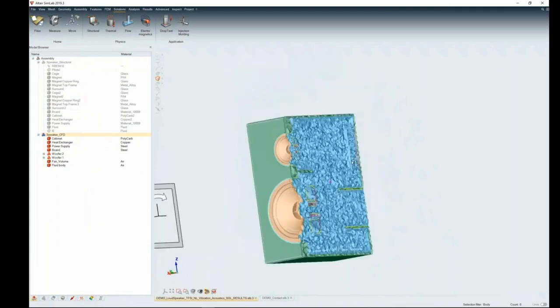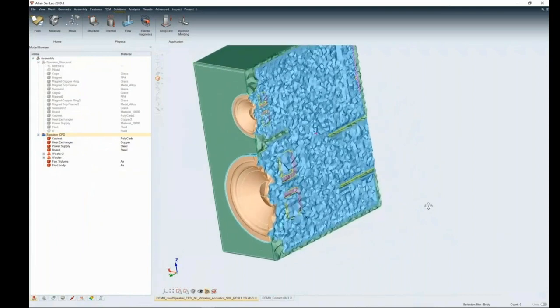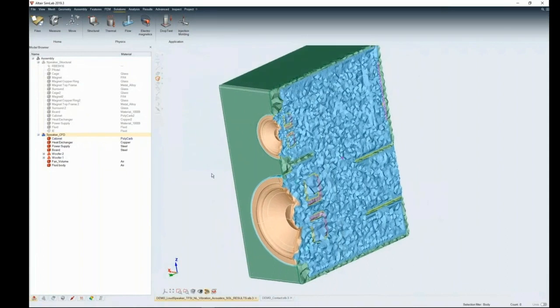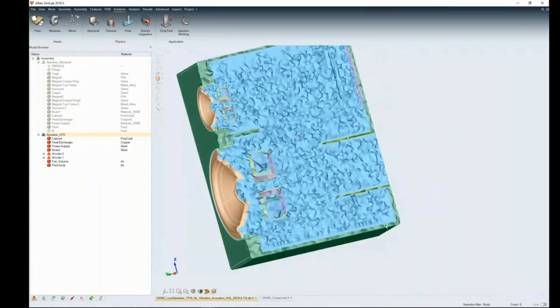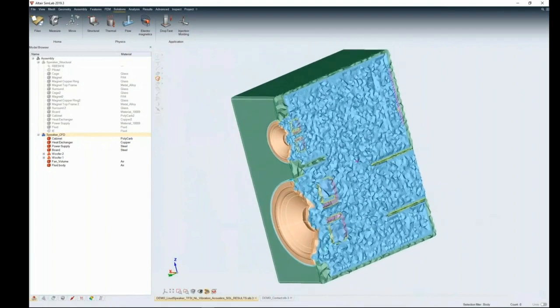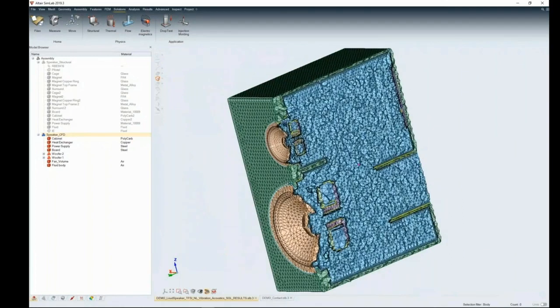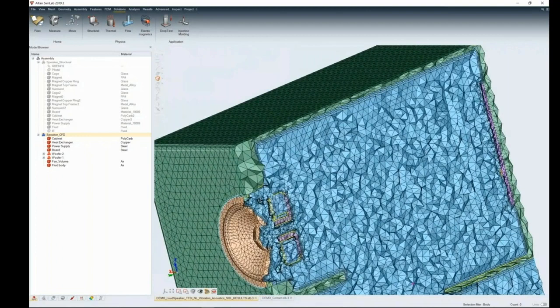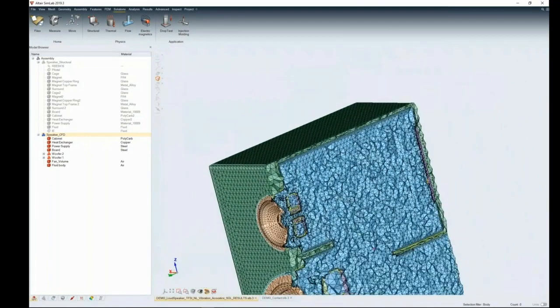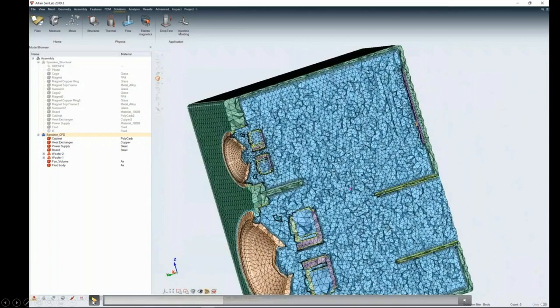Now, let's zoom in to look at the structural mesh out there. And you can see this is a construction in a cut section, and you have the PCB board in the end, you have the microphone speaker in the front, top and the bottom, and the cabinet in the green. Now, in the CFD, the expert sitting in this call would know that you would want to look at a certain number of boundary layers between the parts. And these have to be assigned uniformly, taken care of at every part in the CFD side. I think this is the critical thing.